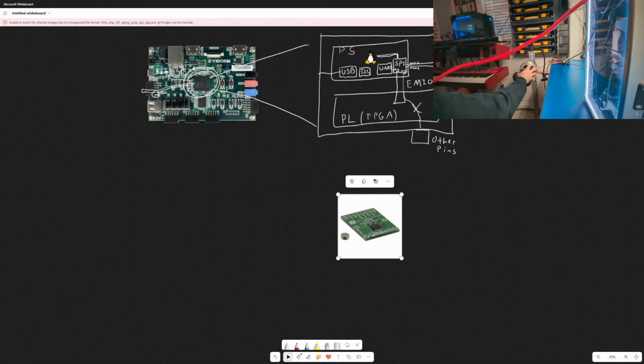These are brushless DC motors. They're not brushed. Brushless means it works based off of magnetism. There are pulses as it goes from point to point, and inside of this there's a sensor called a Hall effect sensor. Each click that you go along, this Hall effect sensor is relaying how many clicks along the motor is.